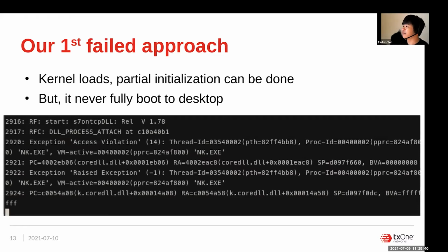And then, with our naive approach, we are met with our first failure. This is roughly as far as we can go before we went with another method. As the firmware requires some checks to special flash and I/O devices, this approach will naturally fail. However, we have done our attempt. We tried to binary patch a great amount of this image and did make more progress into the booting process. But then we decided to go against this route.